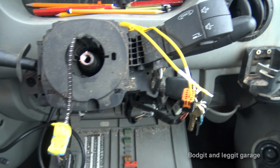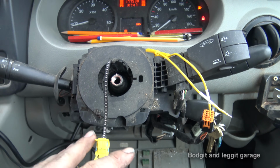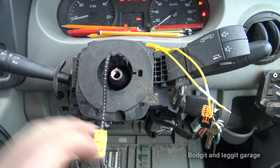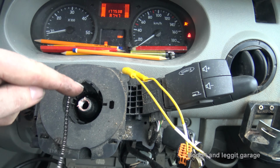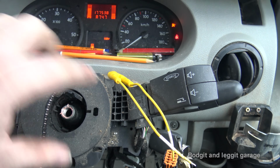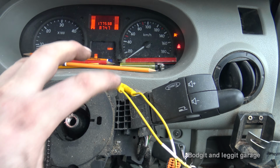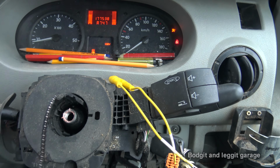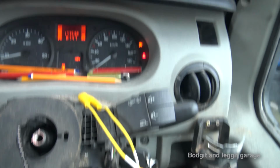So we definitely know, we've tested it from here to here, so we know that our airbag is fine because our light was still on even though we connected our thing here. So we know somewhere internally in this clock spring there's a break, or there's a wear, there's a rub, there's a short, there's something internally in here, which normally does happen as these spin around. So there we go. So that's it.